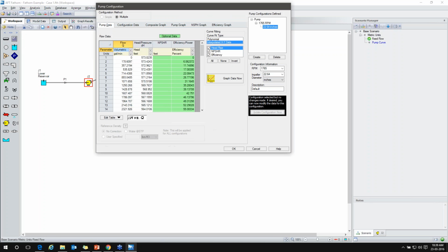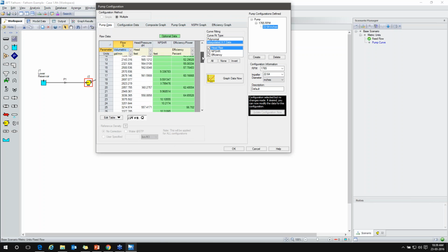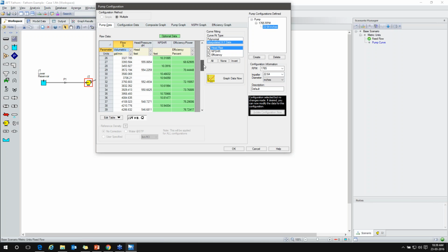You can see all the pump curves which we picked up from the vendor's website are now imported into the system. This is a very intelligent feature of the software, where it helps users to intelligently size the pump and pick up the pump characteristic equations.